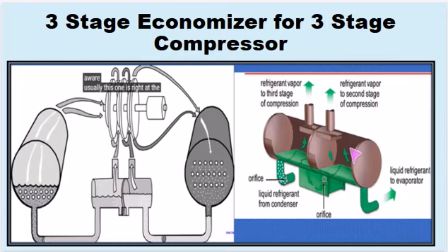It goes through the first compressor. Think of it like a pump that increases pressure and temperature. Then it goes through an intercooler, like a quick cool down stop, before moving to the second floor. On the second floor, second stage, another compressor increases the pressure and temperature even more, followed by another cooling break. The same happens on the third floor, third stage.